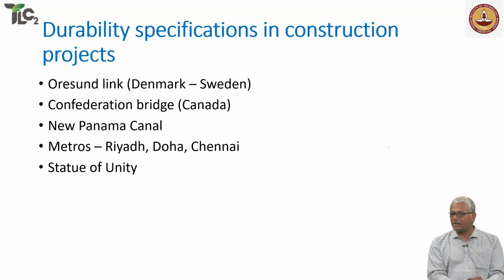So definitely in precast operations, even the variability in durability tests can be brought down significantly, because you have a controlled environment, you have generally a lot more qualified personnel handling precast operations as compared to on-site construction. So ensuring durability in precast construction, or at least in the precast panels, is much easier as compared to doing this in on-site construction. However, if you don't pay attention to the connections on site, then you are creating more problems, right? Because ultimately, correct, absolutely. Because precast, the entire performance is in the connections.